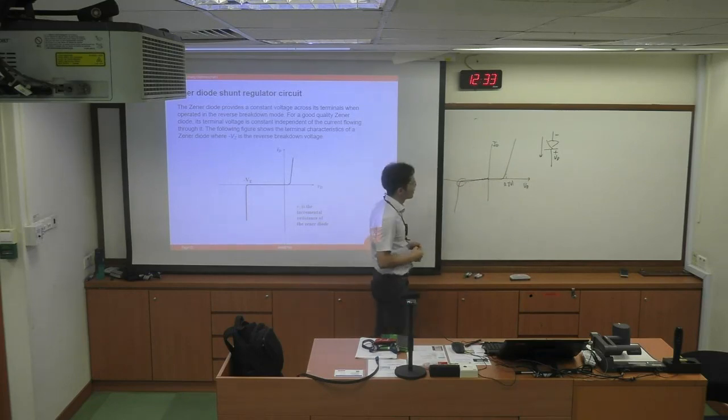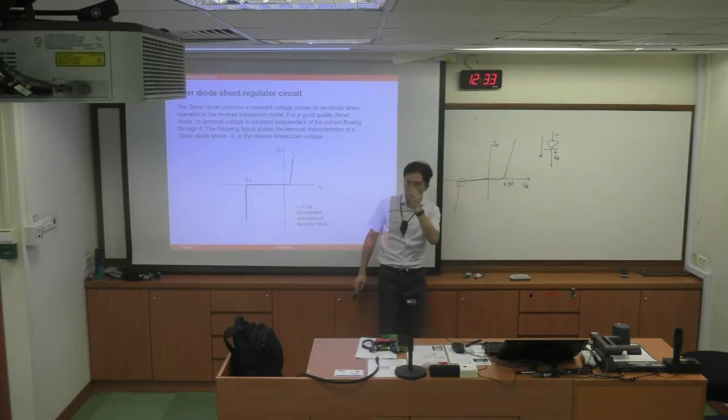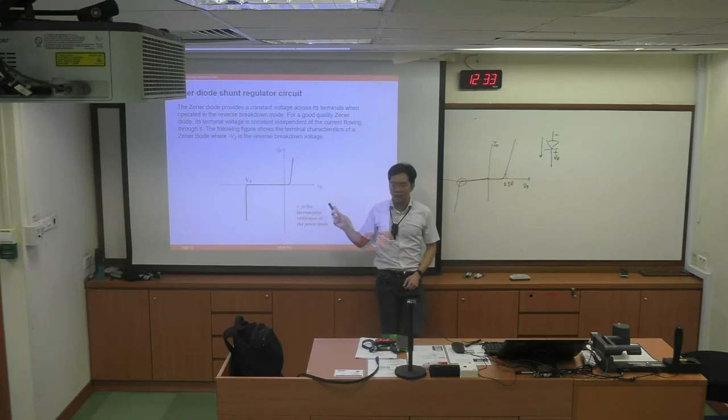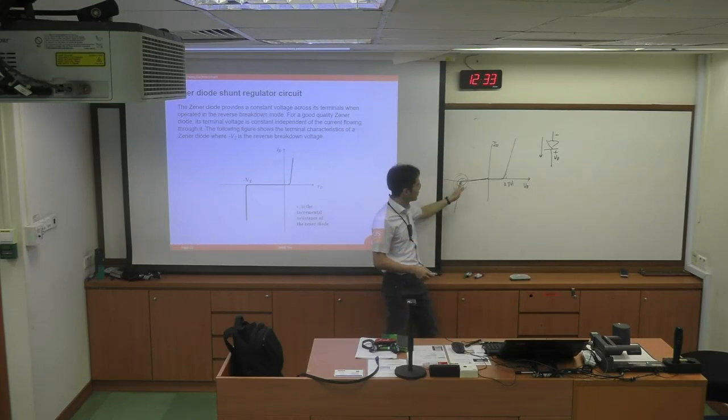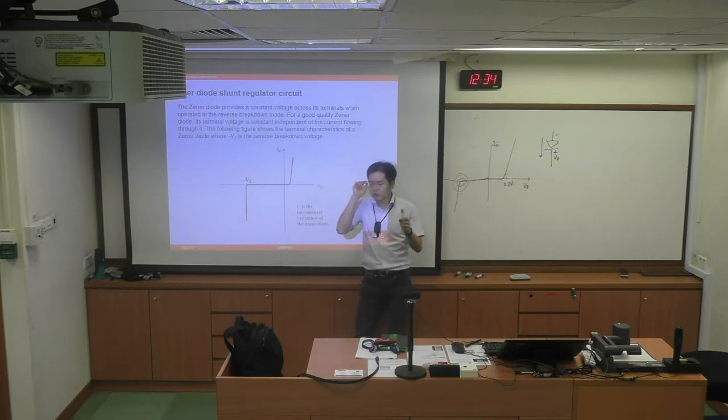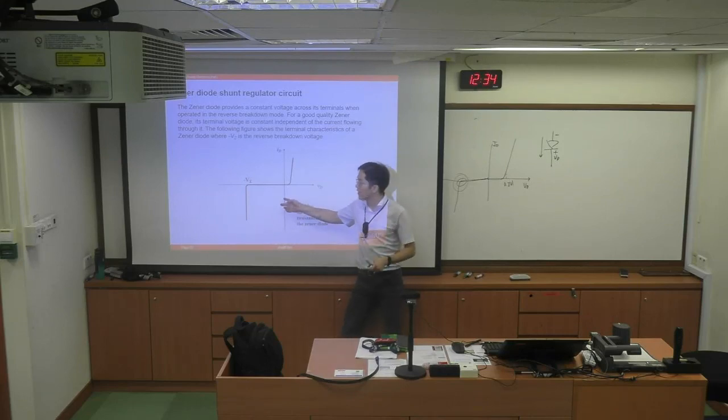Avalanche breakdown happens at typically minus, depending on your diode, it differs. Sometimes minus 7 volts, sometimes minus 12, minus 20 volts. But you don't have a controlled voltage there. Whereas the Zener diode, in other words, the regular diode, you don't use this intention, and you don't typically even go close to this breakdown voltage because that's unregulated and uncontrolled voltage for a regular diode. But there's a Zener diode, where you control the dopant, and you have a predetermined value where it will give way in the reverse bias. And that's a controlled voltage.